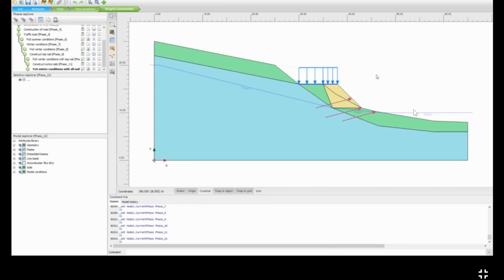But the question is, can we have more information and a better insight of the factor of safety for the upper slope and for the loss of the road? In a PLAXIS finite element calculation, we can only achieve one global factor of safety for the entire model, and the resulting slip surface is the outcome. Now with the limit equilibrium solution using Slope W, we will be able to specify different areas for which we will determine the factor of safety.